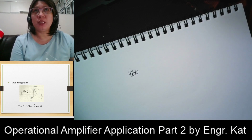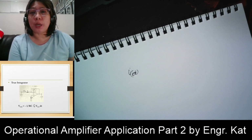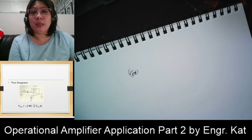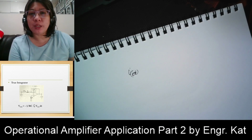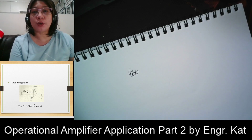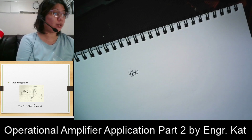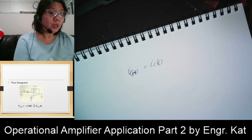Why? If you can still remember our virtual grounding, we said that there is no current that will enter our operational amplifier. So the current flowing across your R is the same current that will flow across your capacitor. Therefore, those two currents are equal.